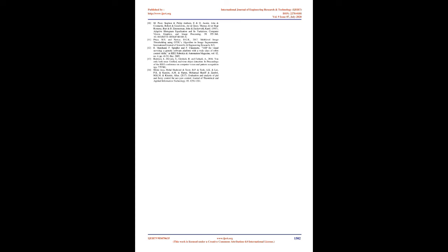Controls module. It computes the composite thruster commands and accordingly communicates the speed and direction of the thrusters to the microcontroller. Sensor input node. Real-time information about the AUV's current position and orientation is acquired through VN300, an inertial measurement unit, IMU, an attitude heading reference system, AHRS, which combines 3-axis accelerometers, 3-axis gyros, and 3-axis magnetometers to give data about the AUV's current yaw, pitch and roll, and a pressure sensor which gives data about the depth of the AUV.